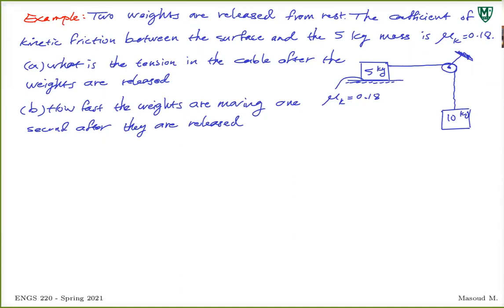Right? And remember the same assumptions we made in statics about ropes and chains and threads. We said they do not stretch. They're always under tension. If there is a rope under compression, it means we can just ignore that rope or chain. And we said the force is the same throughout the rope. These are the main assumptions that we make about ropes, chains, and cables, generally in statics, dynamics, in most courses in engineering mechanics, in mechanical engineering.